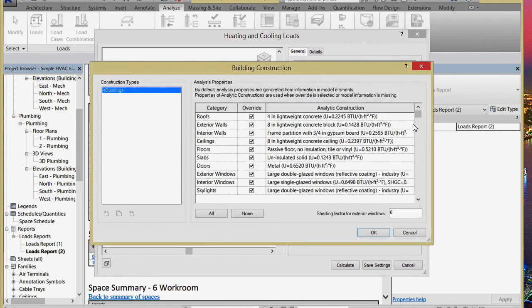Let's kind of change these a little bit. Okay, so as you think about your buildings and the roof that you're likely to put on your building, what sort of R value are you imagining for your roof? Do you have a sense of what the R value might be? 30s. Probably in the 30s. Just in residential construction right now, anything in California for this zone, we need to put pretty much an R30 roof on it.